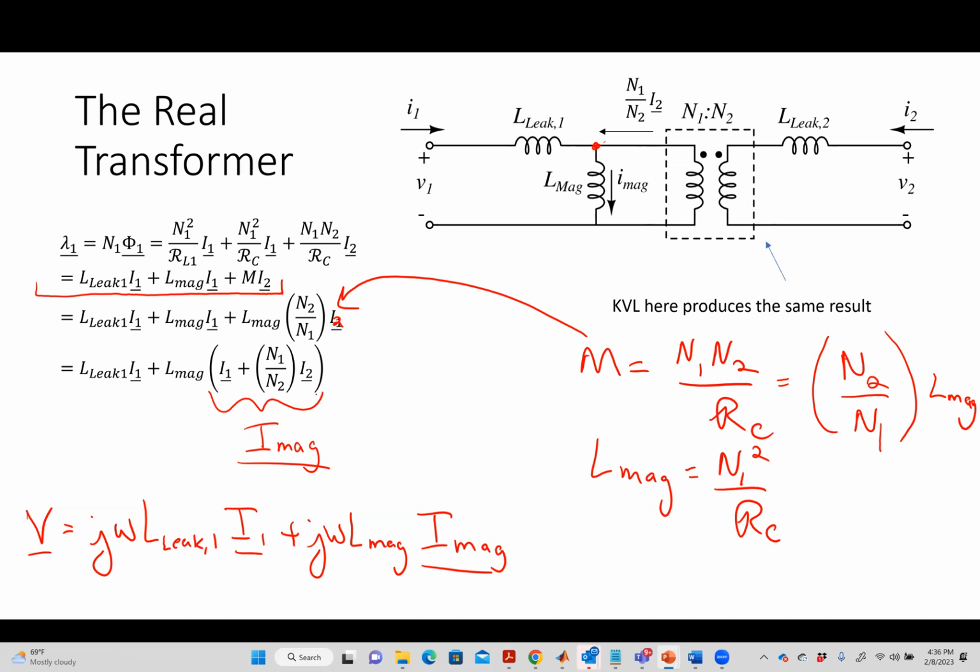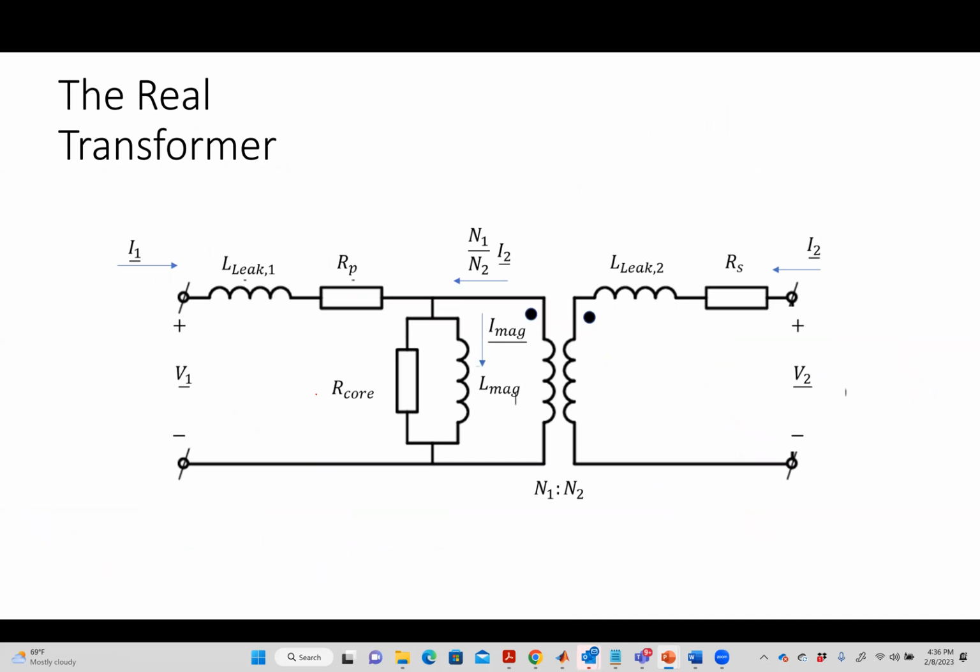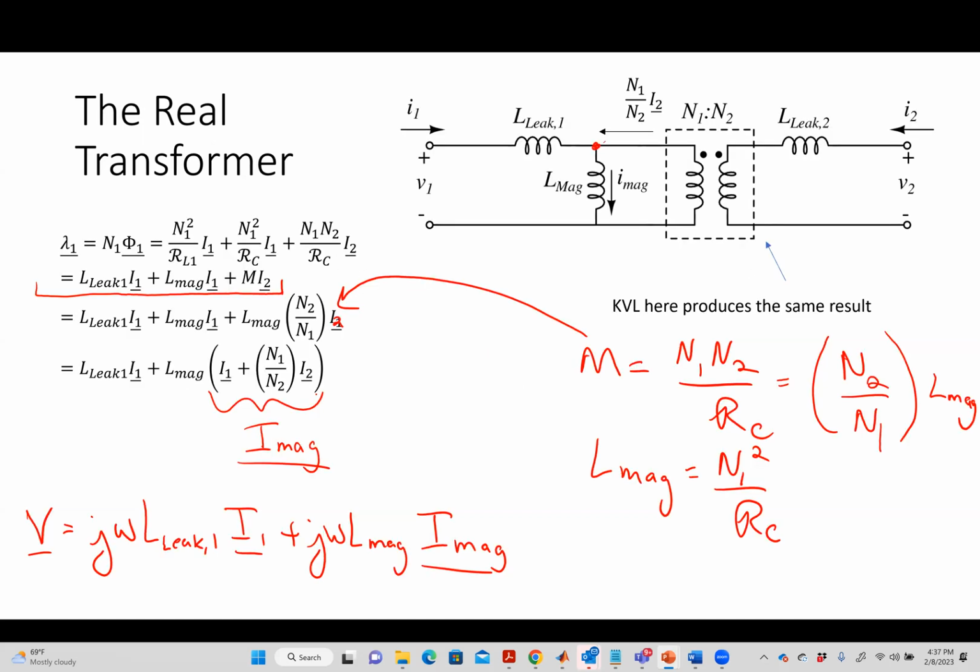We haven't touched leakages until this moment, right? But basically the inductance of the core and the loss of the core were in parallel with each other. And then the other thing which I didn't include is I also probably have a winding resistance, I call it. What's the winding resistance? Yeah, the wire has some resistance to it, right? So at the end of the day, the whole circuit model ends up looking like this thing. Okay. And I didn't include this. I could have written out a whole equation for lambda 2, but we'd be here for another 2 days and you guys would fall asleep.